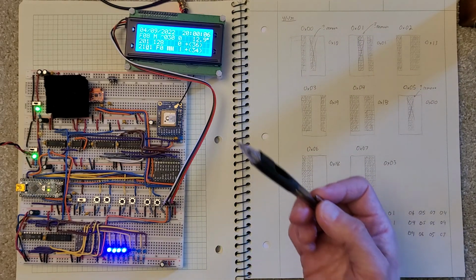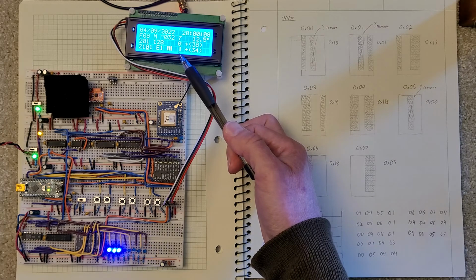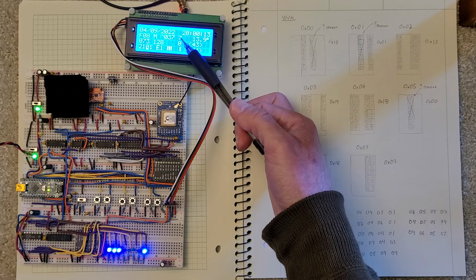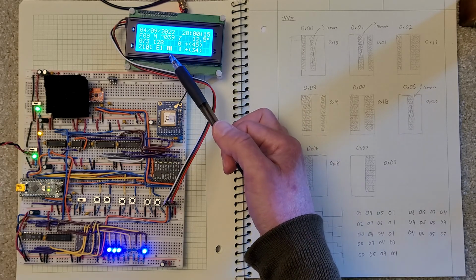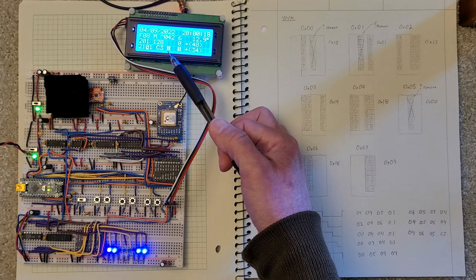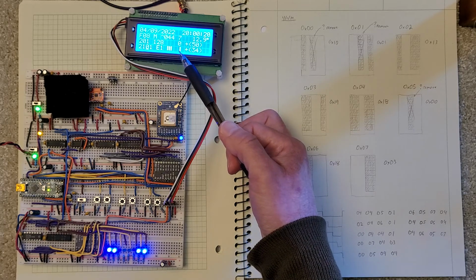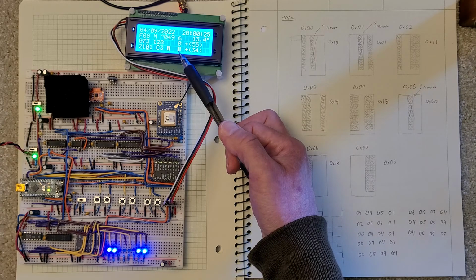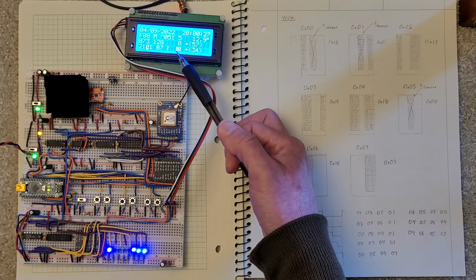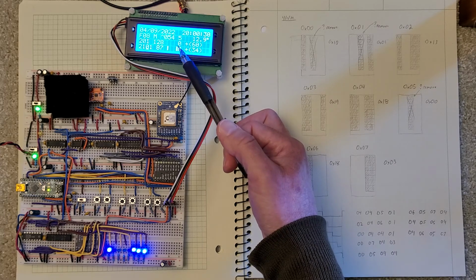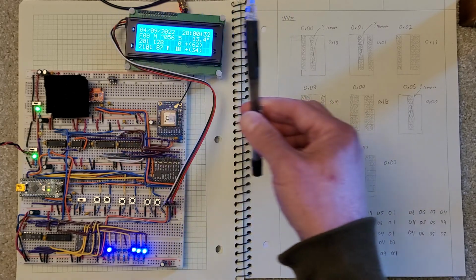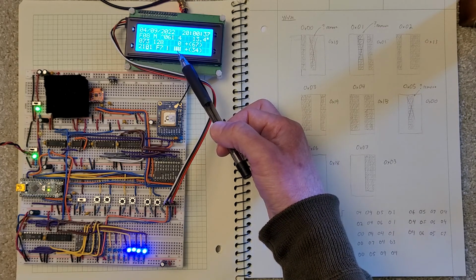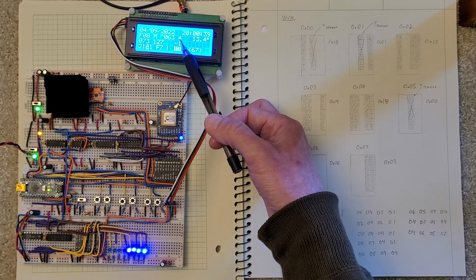The software actually wants to know where the edge is, and this value up here is where the edge is. So I've numbered each of these bits. This is bit 0, 1, 2, 3, 4, 5, 6, 7. And so here the leading edge is at 6. And now it's at 5. And so this basically corresponds to the relative phase of the 10 megahertz clock in relationship to the PPS signal. And that's really what the software is going to look at.